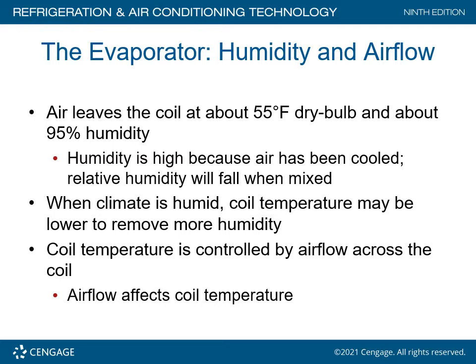If we have too little air, we're going to have frosting, we're going to have freeze up problems. If we have too much air, basically we're not going to remove all the heat that is coming into the evaporator coil from the structure.